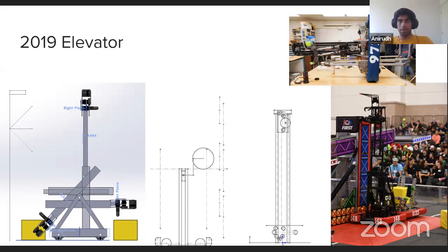If you're going to do something where the free body diagram is really complicated, it's probably good to do stress analysis. There's not really a general rule for it, other than you should have an understanding of the forces that are happening in your system, and stress analysis can really help you with that, if a free body diagram gets too complicated, or you just don't understand it.